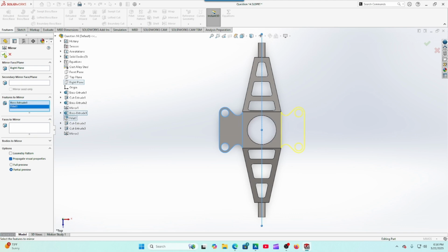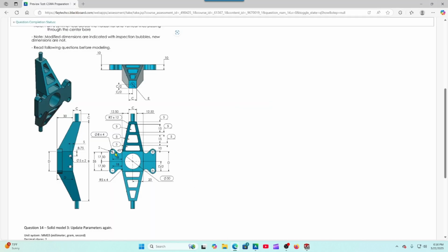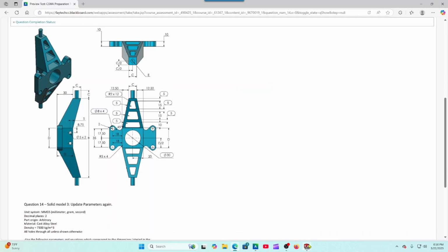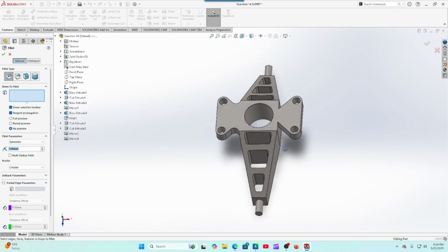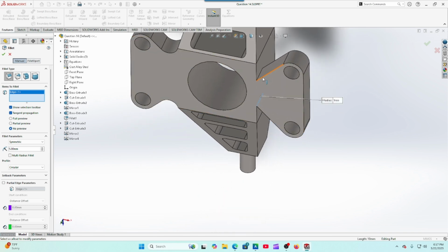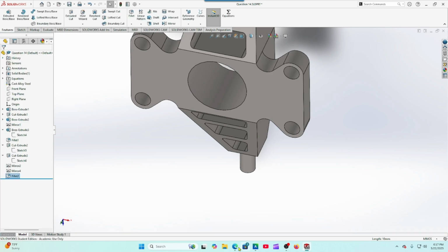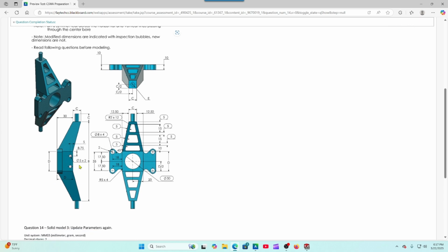So, it may not let us do the fillet. It doesn't always like to. So we'll delete the fillet and it'll put it in there. And then if we go in here and look, it's a radius of 5. So we'll go ahead and do a fillet that has 5 selected already. So we'll do that. And we'll do that. Put that in there. And the thickness is still 10 on that one. And we got to do these two holes. So 8.75 and 5 off the top.